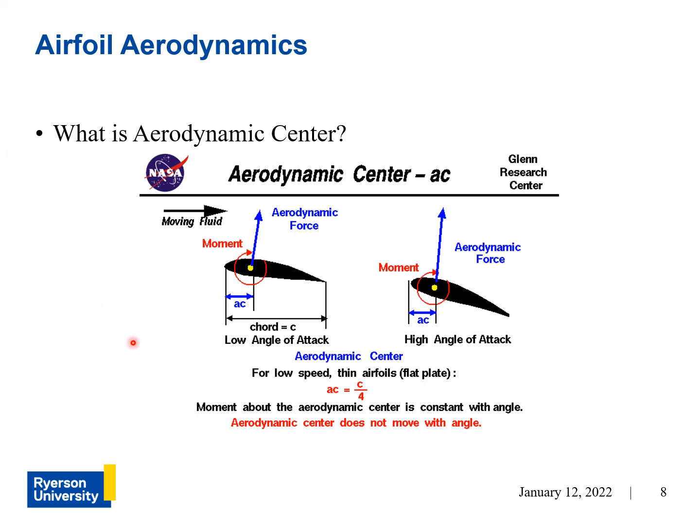And it is important to understand the pitching moment of an airfoil if you want to keep your glider from pitching downwards. So if you know the pitching moment that the airfoil generates on its own, then you will need to design a counter moment so that the net moment is 0, so that your aircraft doesn't pitch down as it glides.